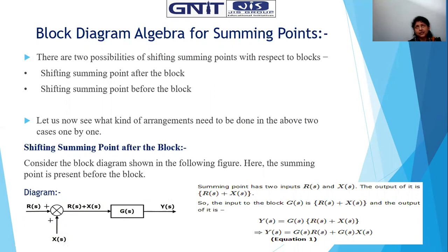There is a convention that while going to the numericals, if the summing point can be shifted towards the left, towards the set point, that will be easier for the calculation. That is from my experience, I am telling you, and you may take it as a trick for the calculation.